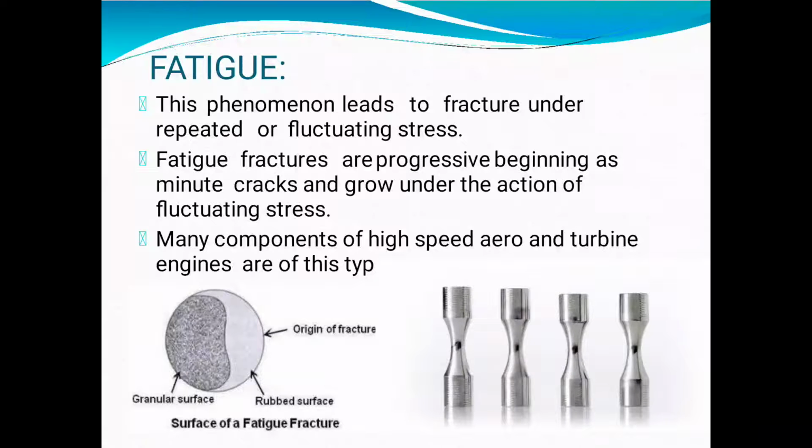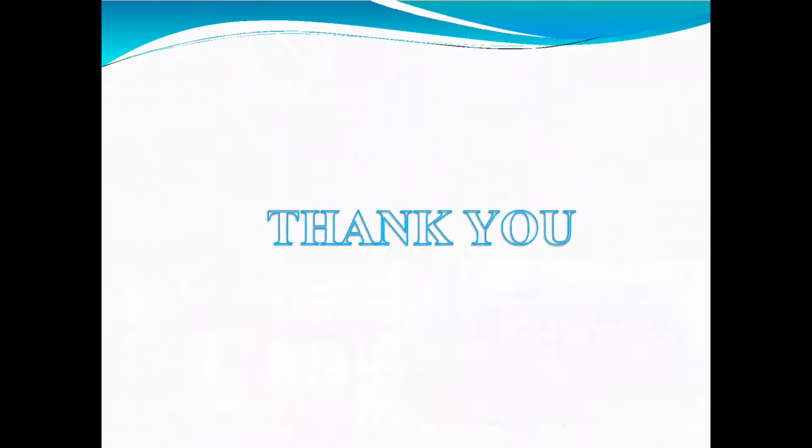Fatigue: this phenomenon leads to fracture under repeated or fluctuating stresses. Fatigue fractures are progressive, beginning as a minute crack and growing under the action of fluctuating stress. Many components of high-speed aero and turbine engines are of this type.